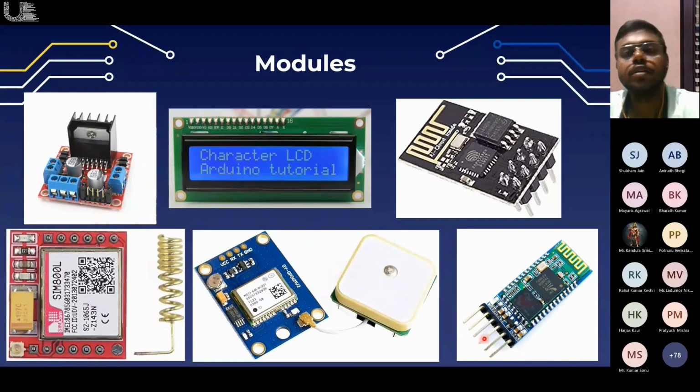This is the Wi-Fi module. The Wi-Fi module is used to make the Arduino board Wi-Fi ready. And we can use it to connect to a Wi-Fi network. So for the type of applications like data collection for various machine learning projects, you want to collect data for temperature or soil moisture content, humidity, and you want to continuously log it somewhere in the cloud. So that time you can use this Wi-Fi module to log it, and then it can be programmed to store at some location, or you can use some API to store it at some location in the cloud.